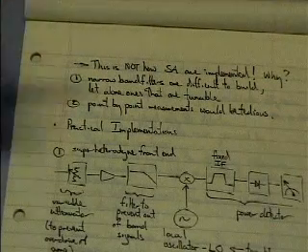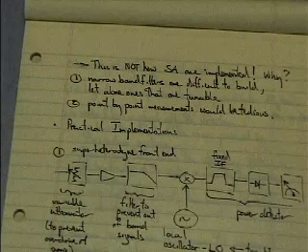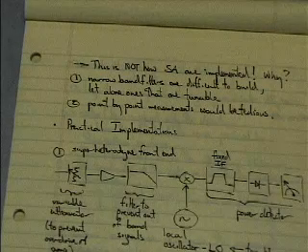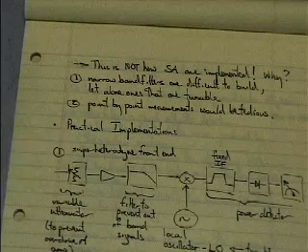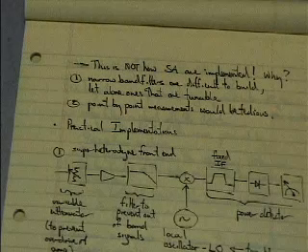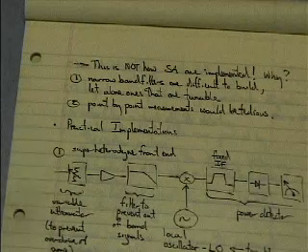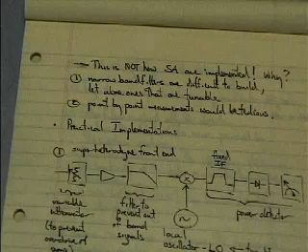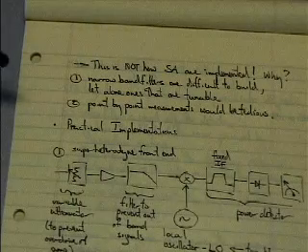The other part is that doing these point-by-point measurements of power for particular frequencies would be very tedious. So what we want, and what the spectrum analyzer does for us, is allow us to look at the power values over a range of frequency. For example, if I'm interested in the power between 10 megahertz and 20 megahertz, then I could set up the spectrum analyzer to look at that particular region, and it will display the power of all the signal components in that range.